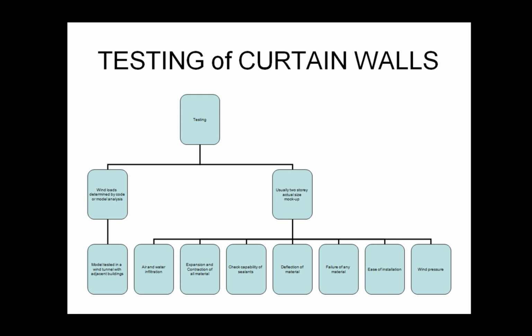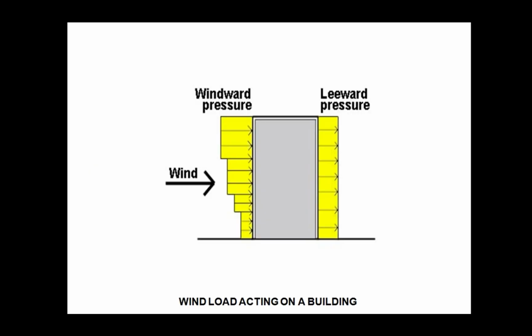Okay. And then obviously wind pressure, just like you would in a wind tunnel if you don't do the wind tunnel test. As we all know, the higher up you go in the building, you're going to have higher wind pressures, just more exposure to wind, fewer wind breaks, buildings and things around you to slow the wind down. But the reaction you want on the other side is a distributed reaction, where you're not taking extra load.